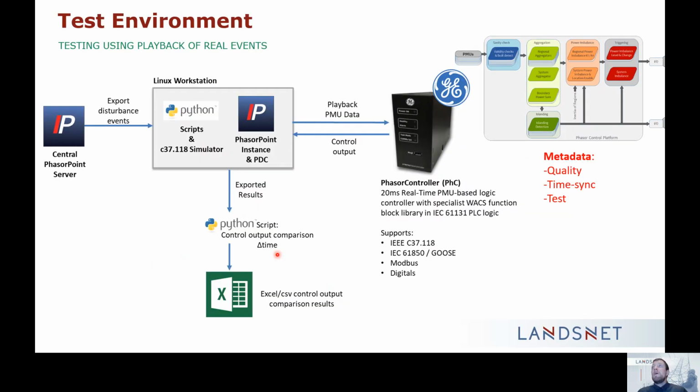A little bit into the test environment. What we've been doing in Iceland is use the data we have available, and we use a Phasor controller, which is a product from GE, alongside the Phasor Point, which is the wide area monitoring software. And in this, we're using the classical synchrophasor data, IEEE C37.118.